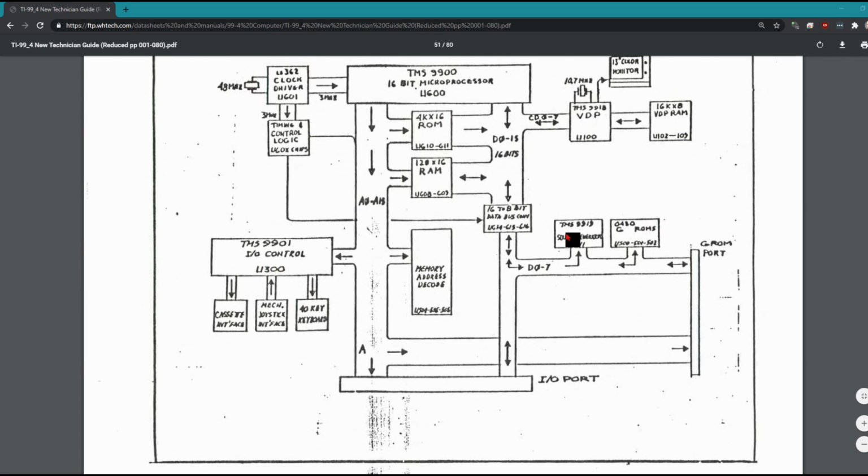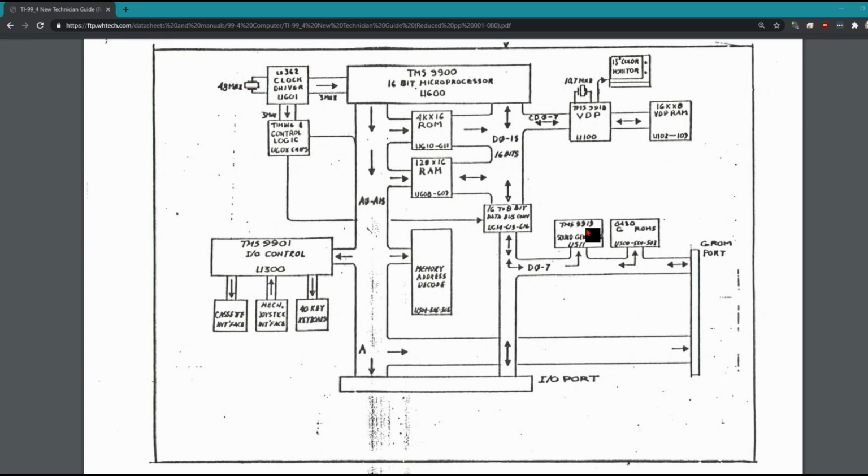Now there's something I haven't tested yet. The sound generator chip is a TMS9919, but it's very similar, or it is the same as the chip that's in the Tandy 1000. And what's interesting on the Tandy 1000 is when you first turn on the computer, you hear a tone out of the speaker very briefly, but as the computer initializes, it shuts off the sounds from the chip. If there's a problem with your Tandy where it's not actually initializing the ROM, so it's not booting at all, what happens when you first turn it on is you just get a continual tone.